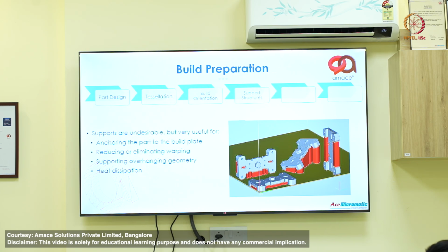In this image you can see multiple parts, actually the same design, oriented in different ways. There is no standard solution. We need to find the best compromise, because each part has different support requirements. According to our application requirements, we have to choose the right orientation.